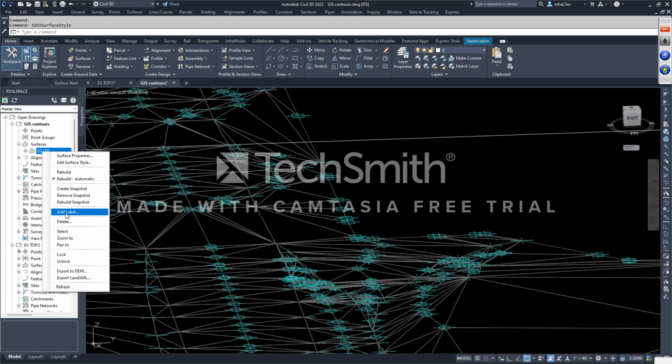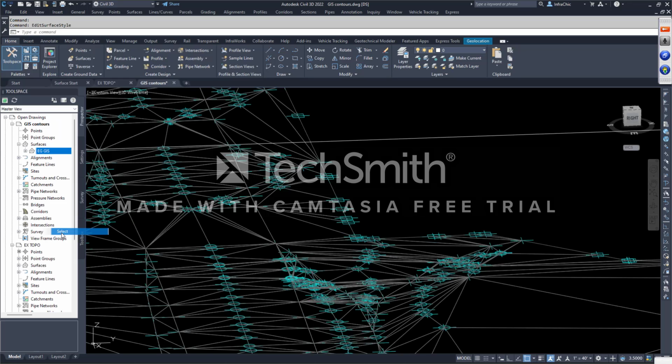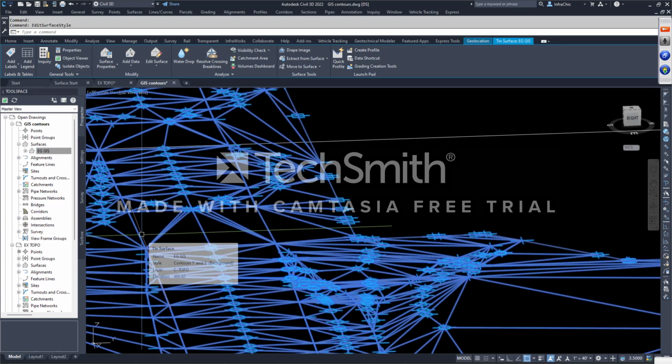I can add labels, so adding labels like contour labels, slope labels, spot shot elevations, that type of thing. I can delete the entire surface object. If I hit delete, it goes bye-bye. No matter what's in it, it's gone. Unless this surface is referenced into another object like a corridor or maybe a profile, then it won't go away. I can select the surface. When you select something, it always highlights.